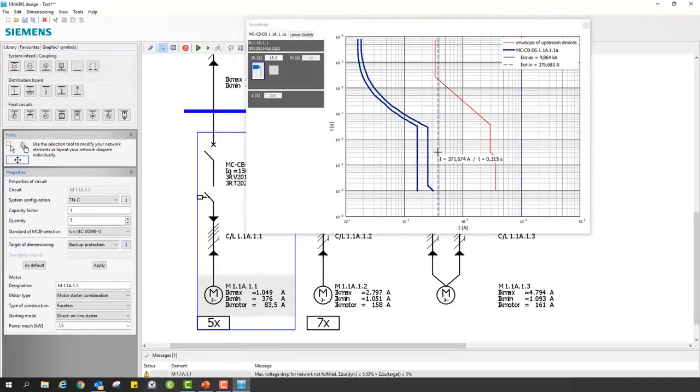As you remember, the maximum short circuit current that we see here is the 3-pole short circuit fault, and the minimum is the 1-pole short circuit fault. The most common short circuit to happen is obviously the 1-pole short circuit.